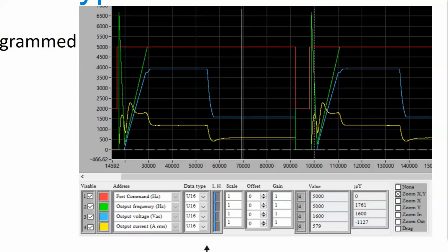And so you can use this function to decrease the output voltage. And by decreasing the output voltage, you can see the output current decreasing quite a lot. So even though the escalator will run at the same speed, because the output voltage will be half or even less than that, and then you also have your energy consumption. Of course, the drive will detect if some load is added to the motor, to the escalator, then the drive will automatically increase the voltage back in order to get the right amount of torque.